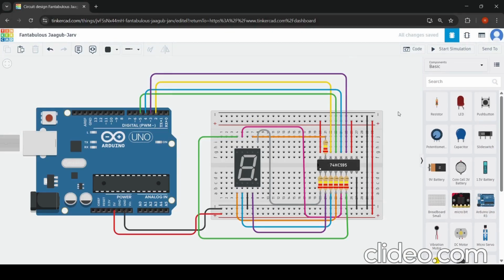So this is the circuit diagram for our project. I am currently using common cathode. I will also show you the common anode. But first of all, let us discuss common cathode. So you can see a total of 10 pins here, right? The two middle pins are the common pins, and the rest of the 8 pins are the digital pins for the LEDs. And this is the pin called DP, that means decimal point.